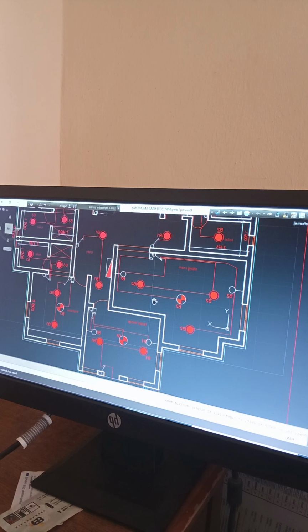Is that okay? So likewise, in this place we'll have a sitting room. As you can see, the sitting room light arrangement. You have your fan regulator. Then we have a three gang switch. The three gang switch controls all this light. If you look at it, you see how it is interconnected. And as you can see, they are numbered B2, B2, B2, while this one was B1.